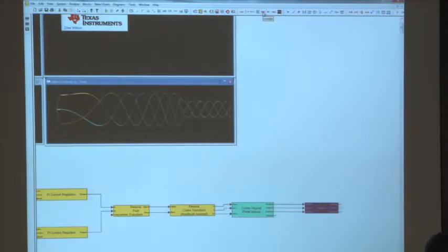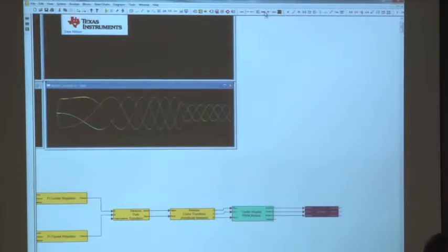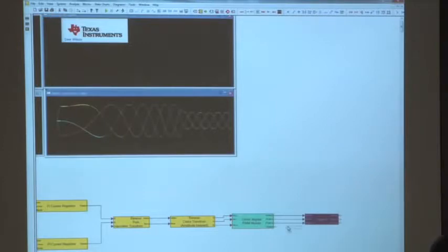It's kind of right next to that symbol that looks like a diode, but it's called VAR. Click on that and put that on the output of, or close to the output of the sample pin. And it should drop a little block that says variable in it. Let's double click on that, and let's call it something creative, like sample. So you double click on that, change the name to sample, hit return.